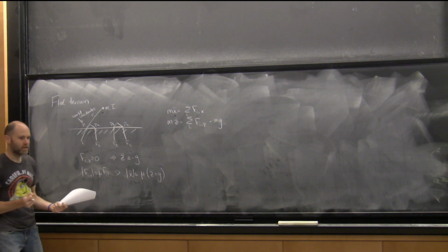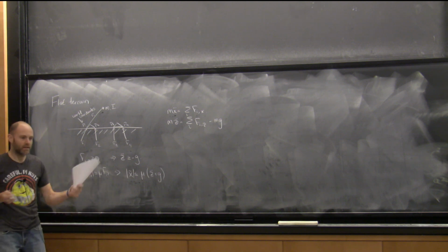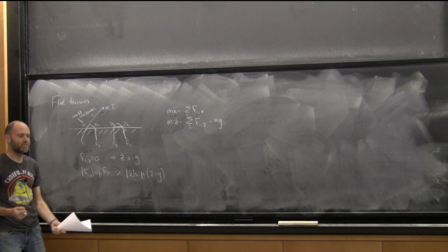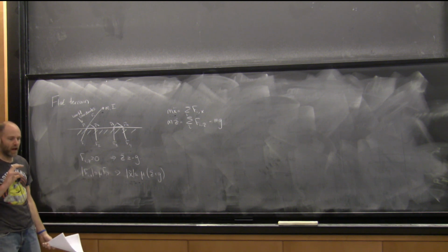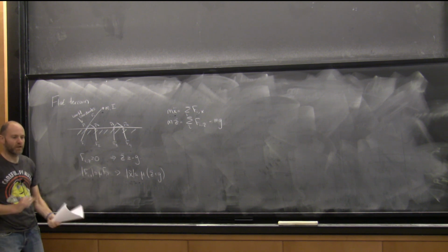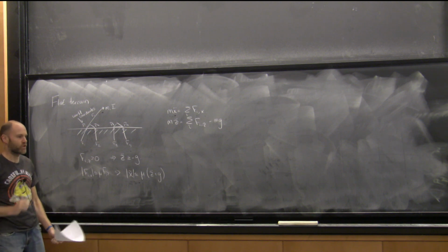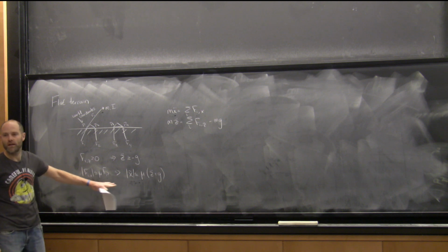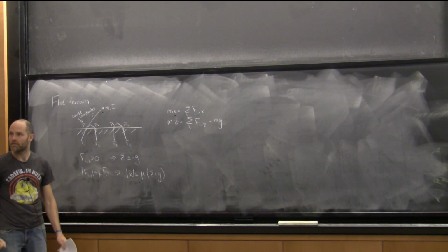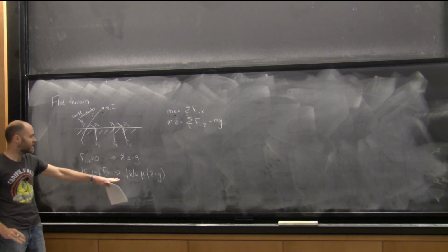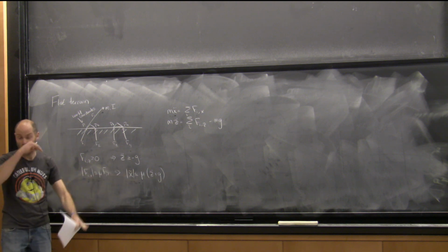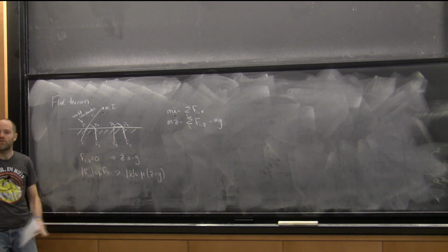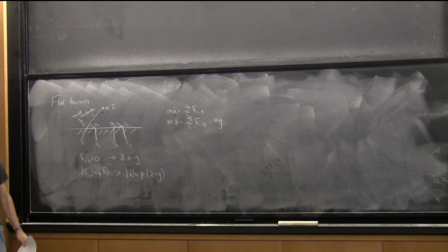So if you think about writing a problem of getting this humanoid through an environment, I'd like to rule out very quickly that I can't do that center of mass trajectory, because there's just no way I could possibly do that given the force opportunities I have. So any constraint we can pull over into the center of mass simplifies my search space a lot.